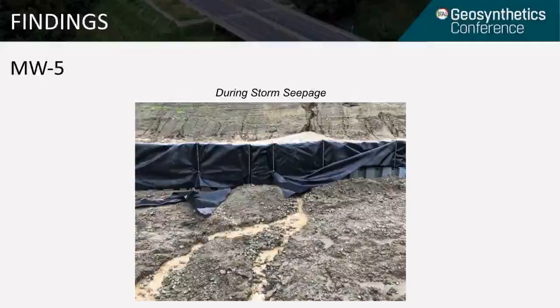While this basin didn't experience any stability issues, even when filled to capacity with 4 feet of sediment and water, it did experience some seepage under the toe of the barrier wall, and this was due to the plastic liner not continuing along the inside of the barrier wall basin, and also due to small irregularities in the ground surface, which created gaps for water to flow through.